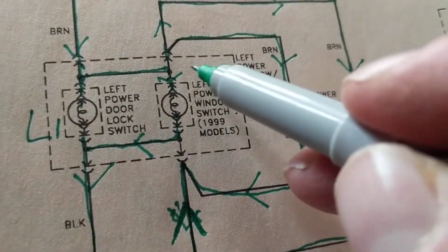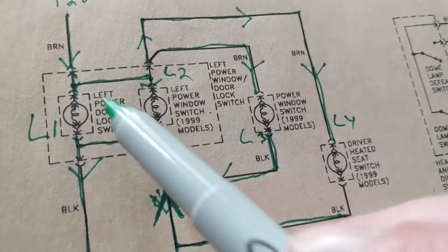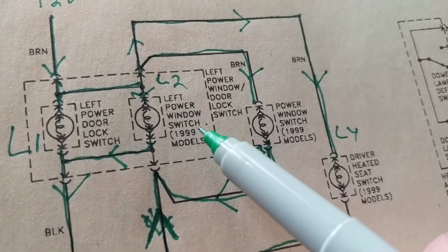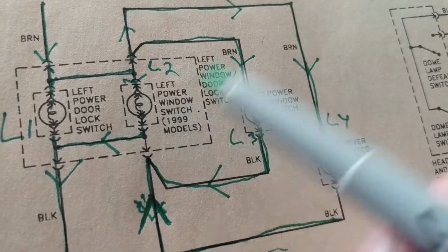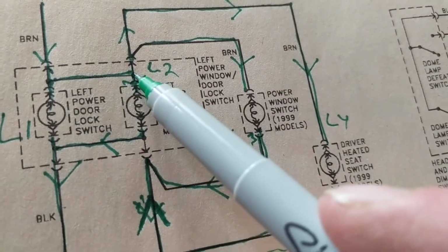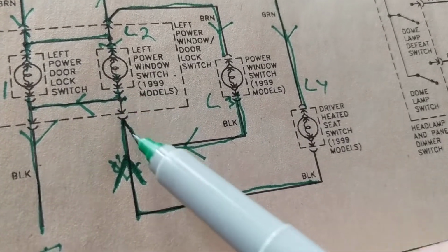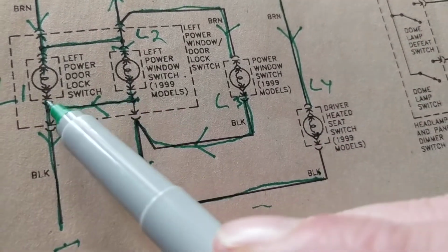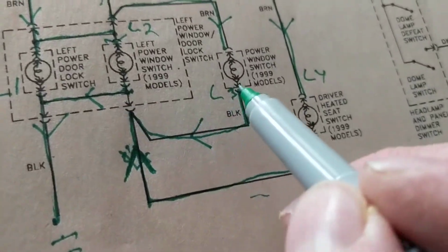It's lit. L2 and L3 and L4. How are we going to get L2 lit? With the left power window switch. Right? We're going to press on the window switch to activate it. So current now flows here. It has another path to go here to light it. Now the problem is, where's the current going to flow? Is it going to flow back here? No. Is it going to flow back up here? No. Is it going to flow back up here to ground? Yes. Why? Why will the current go here and why will the current not go back up here?